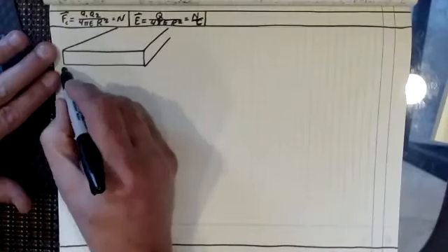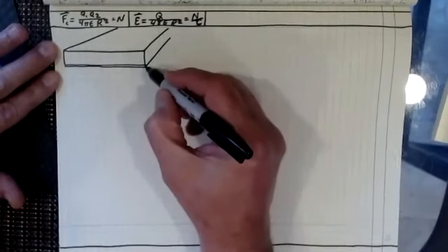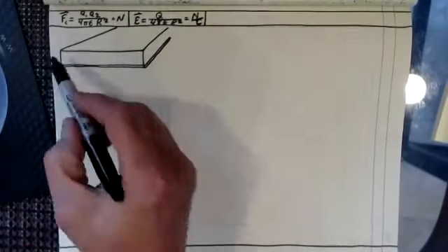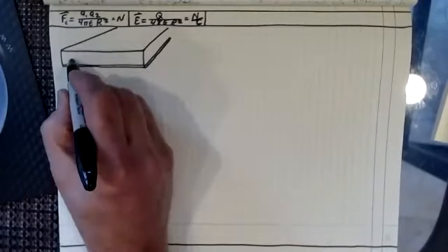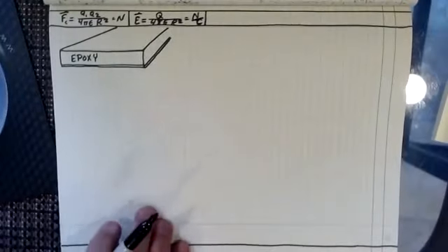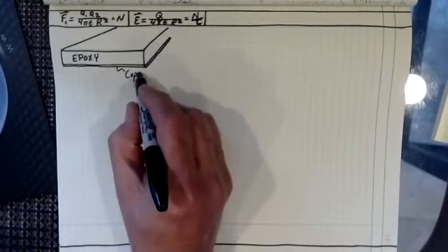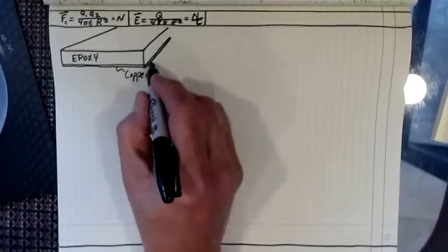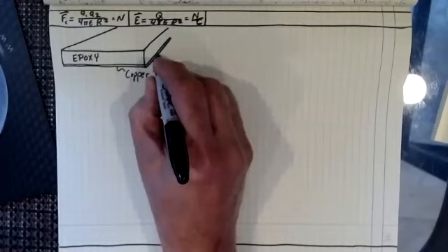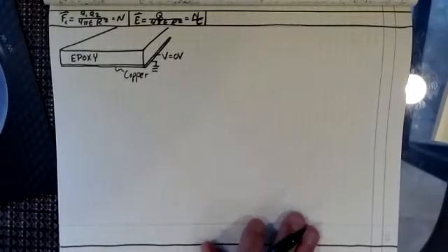Now, let's say that I have down here on the bottom, I've placed a ground plane, right? And that ground plane, I've solder waved that over the entire bottom. So the entire bottom of this epoxy, right? Because this is a printed circuit board. So the middle of it is going to be epoxy. That's what printed circuit boards are made out of. And so I've now coated the bottom with copper. So I've got a copper ground plane here, and then I actually ground the bottom of it so that we know that the bottom's voltage is going to be 0 volts, right?